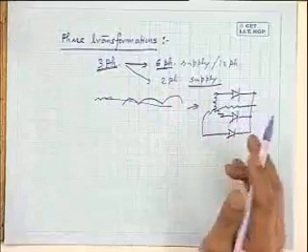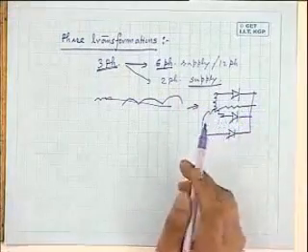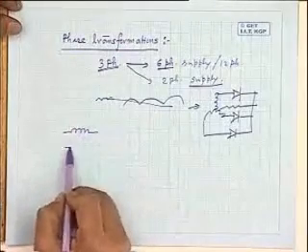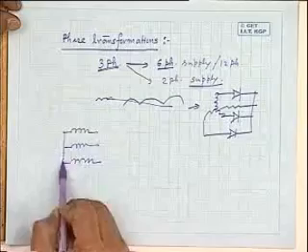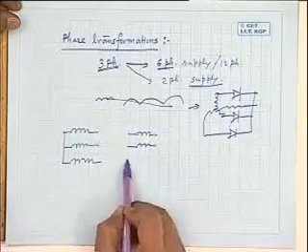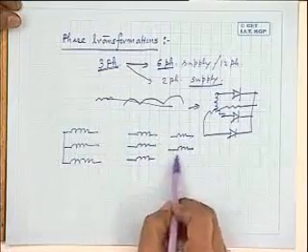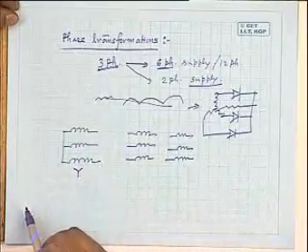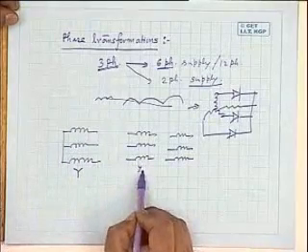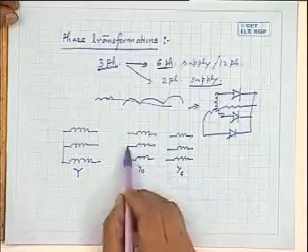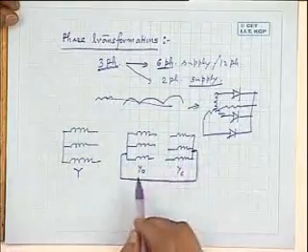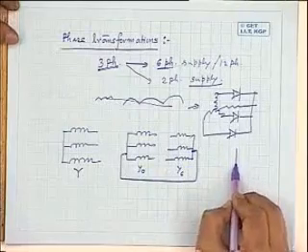Now anyway, I will not digress to that. But suppose the problem is, from a three-phase supply I want to get a six-phase supply. So how can you do it? You now have a transformer which has two identical secondaries, like your zigzag transformers. See, this I will quickly tell because there is nothing serious about it. So you have got two identical secondaries. I will not draw like this. Instead of connecting in zigzag, what you will do is, suppose the primary is connected in star. This one you connect YY0 and this one YY6. So this way and this way you connect. And these two you short.